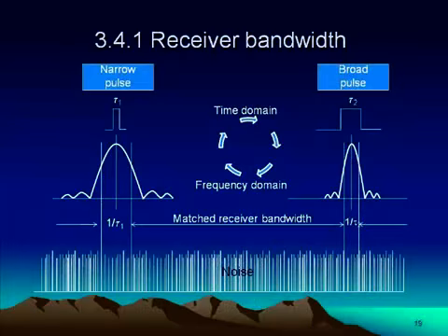So, it is preferable to go for a better antenna design than trying to increase the radar transmitter power or reduce the receiver sensitivity. So, simplistically, the smaller the radar pulse width, the larger the required receiver bandwidth and also the receiver noise floor. Here you can see in slide 19 the requirement of receiver bandwidth.